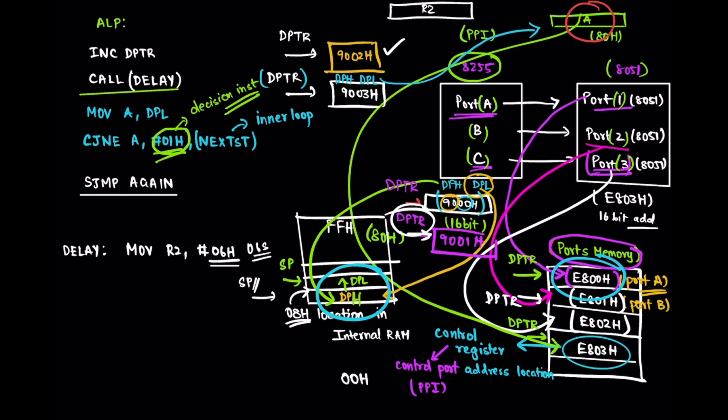So this short jump again is going to create an infinite loop in which the LED is going to keep on switching on and off based on the patterns given to it. And that is what we wanted at the first. We defined something called again and then MOVX A, @DPTR, right? So this infinite loop, we want to execute it continuously. So that's why we are going to end the outer loop here.